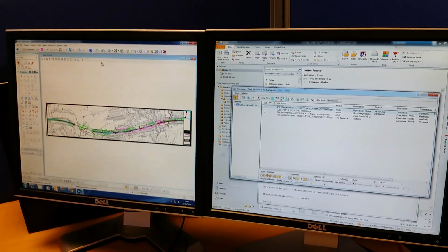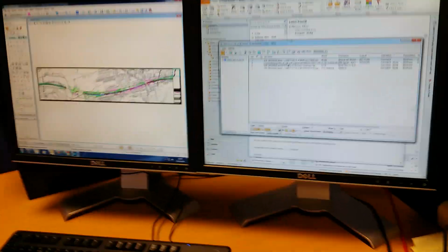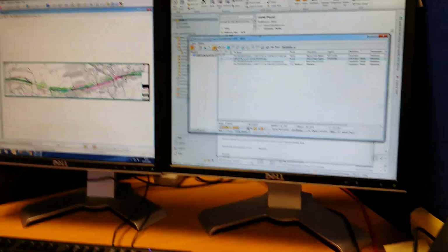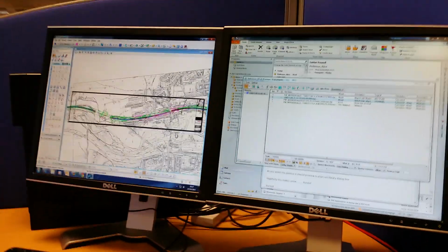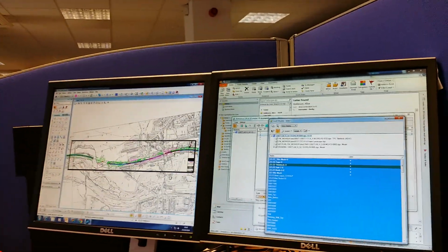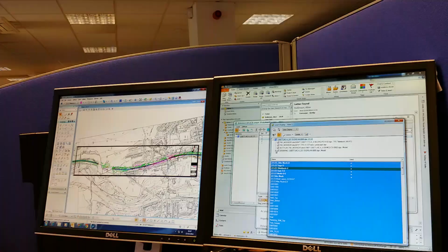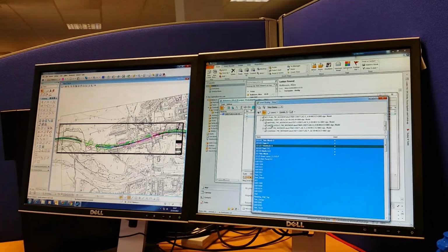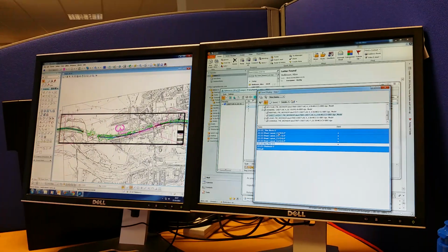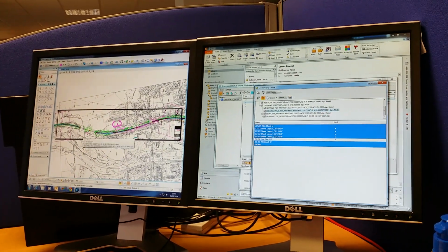Open the reference file. Select for drawing. Delete for clip. And that gets you the full extent. Then open up the level display. Go to drawing, sheet layout. Turn the pink outline back on so you can see where you need to go.